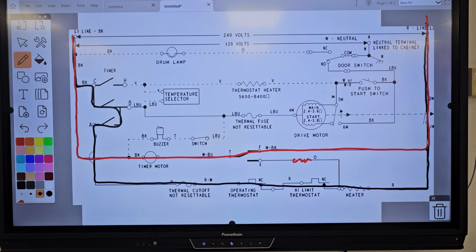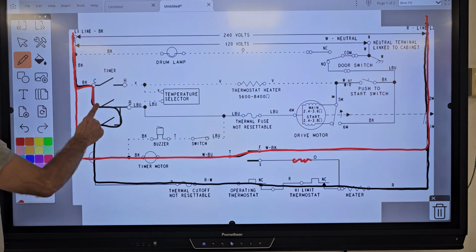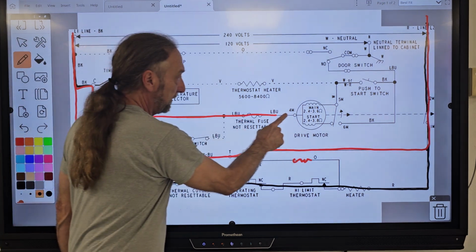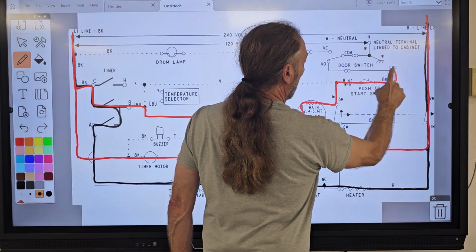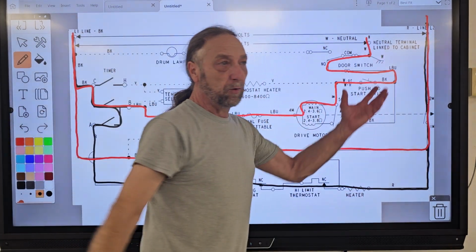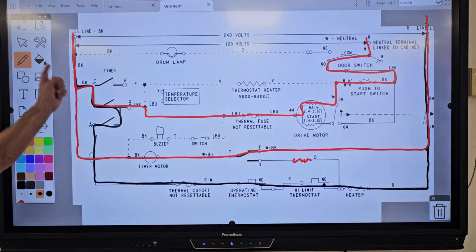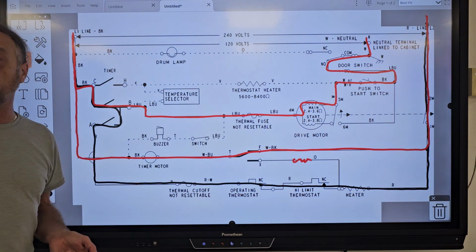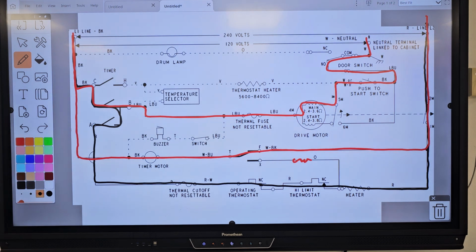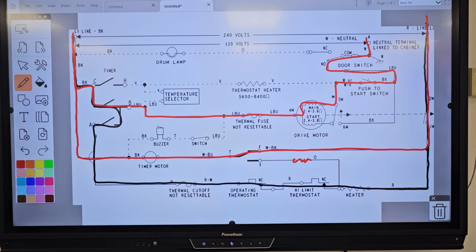But the other thing that happens is that I told you the motor's running, right? So if we looked at that motor circuit again here, the red lines in this diagram are what we know is running. The black line is the circuit that has the problem. But what just happened there? Can you tell me something there? The timer switches close. Which one?